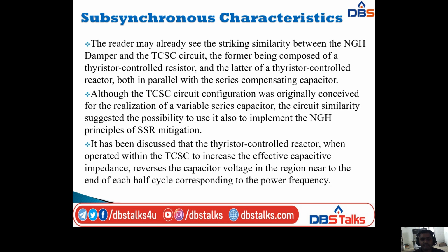So it has been discussed that the TCR, that is the thyristor controlled reactor, when operated within the TCSC to increase the effective capacitive impedance, reverses the capacitor voltage in a region near the end of each half cycle corresponding to the power frequency.